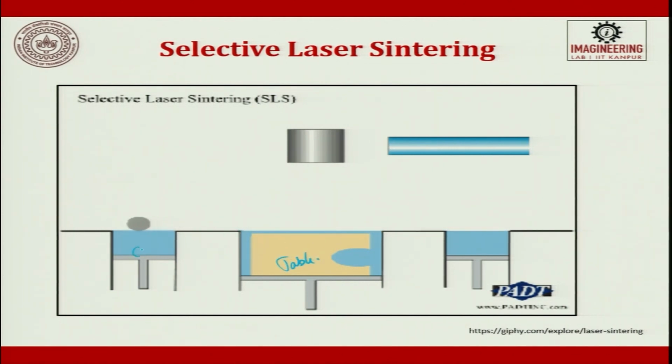This is the canister or can, right? People call it a can. So, once this roller goes to the other extreme end, you can see it will smear powder and go, and once it is done, the laser gets activated and it tries to cure. So, in this way, this can go down, this will go up, alternatively, and try to generate functionally graded material.